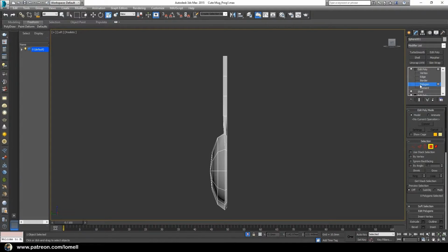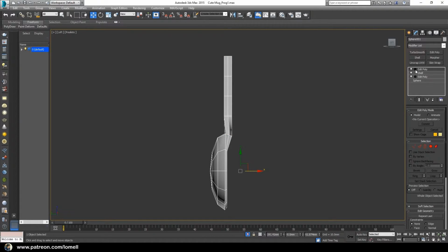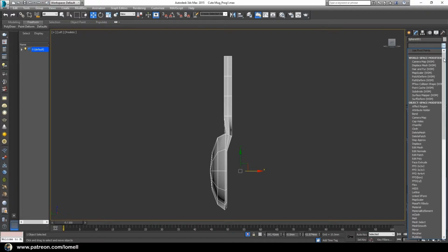and make sure that you are still in polygon mode. Select these polygons, and using the scale tool, let's scale it into X axis and move this in Y axis. Okay, and now let's exit into our editing here. Click that, minimize that, and add turbo smooth modifier. And if you cannot see this turbo smooth modifier over here, you can just browse that under modifier list